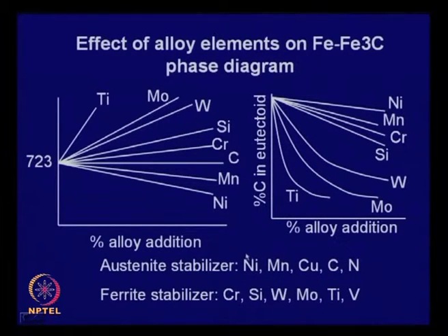One very common austenitic stainless steel, many of you are familiar, has a high amount of nickel and is austenitic, and austenite is non-magnetic. So, whenever you go and buy stainless steel, you check it with a magnet. That says that it has either a high amount of nickel or manganese, which makes the austenite, normally stable in plain carbon steel only at very high temperature, stable even at room temperature.